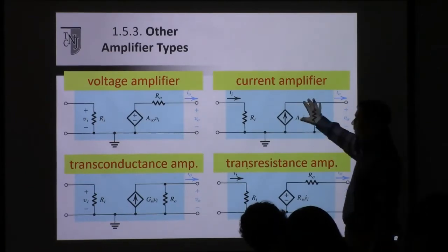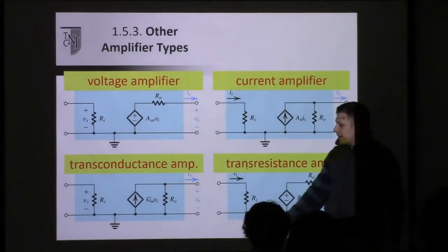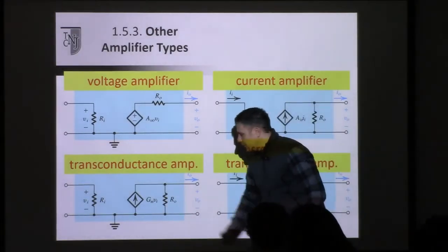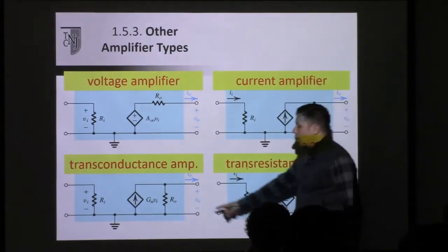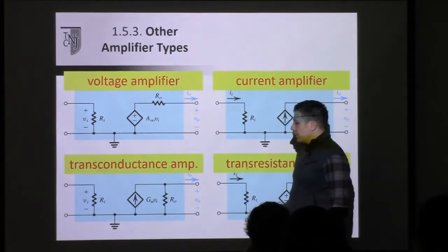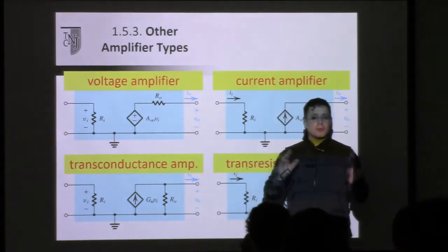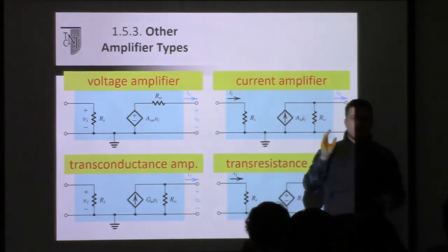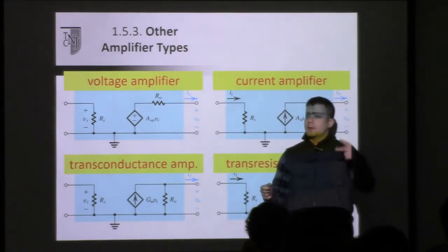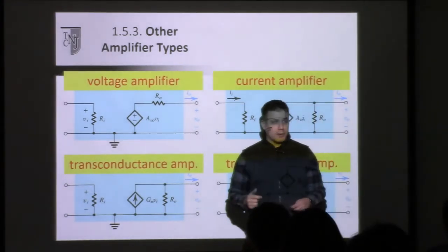And then if we jump from here down to here, again, these two look exactly the same, except for this little piece here, where instead of having our dependent current depend on another current, it's dependent on the voltage. So there are four different permutations of input and output. Your input can either be voltage or current. Your output can either be voltage or current.